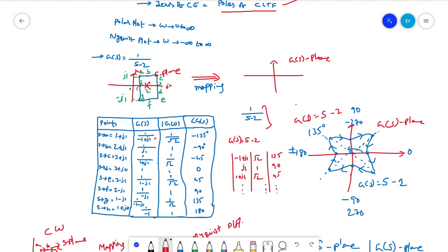One more point I want to make here is that whatever methods we discussed till now on stability criteria are based on the pole location. In the root locus, if the poles are lying on the left half of the S plane, we said that the system is stable. And coming to the Nyquist and Routh-Hurwitz criteria, based on the sign change, we estimated the stability of the system.